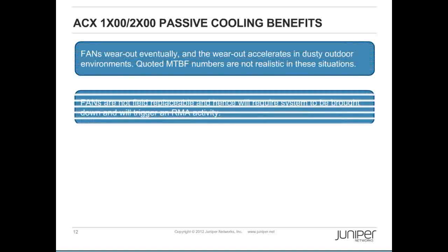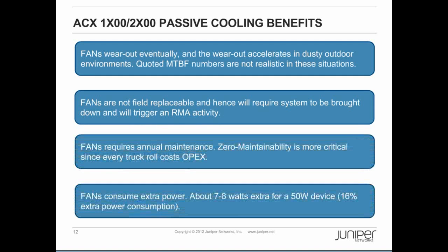We talked through the platforms, what lineup they have, the software features, and the architecture that we propose. I've mentioned passive cooling, but I just want to use this slide to walk you through the benefits of passive cooling. Whenever you have fans, especially in a dusty environment, anything that moves breaks down. The dustier it is, the quoted MTBF number won't be realistic. With no fans, passive cooling will remain robust and highly available even in the most dusty environments.